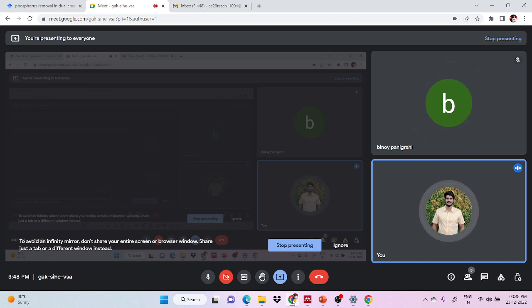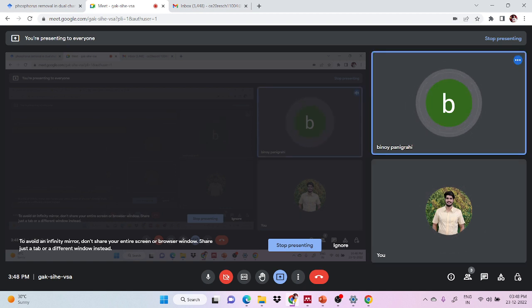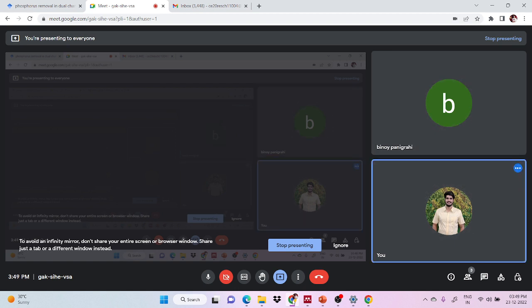In short circuiting, what happens is a portion of the liquid leaves the tank at the exit point before the bulk liquid. Do you understand? A portion of the liquid gets out of the tank before the bulk liquid, though they have entered the tank at the same time. Means the total volume doesn't exit, a portion stays back. Yes, a certain amount of liquid gets out, though the bulk of the liquid still remains in the tank.